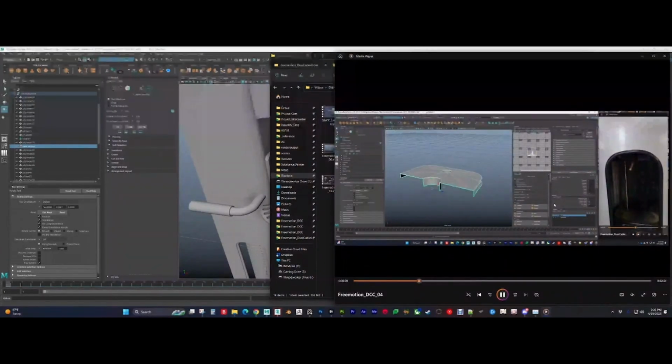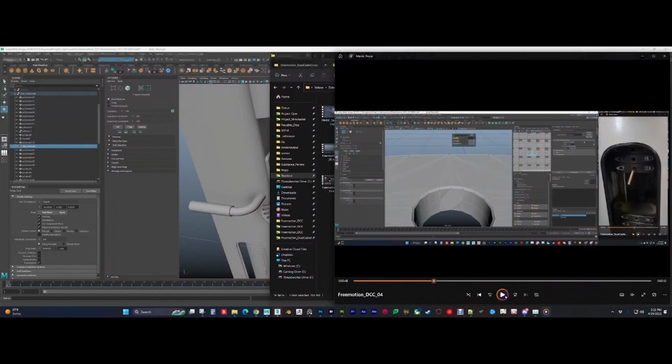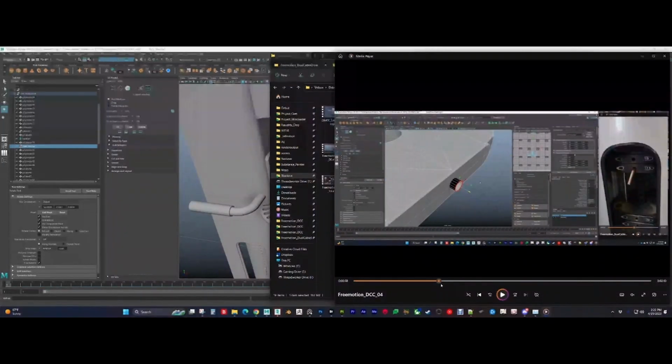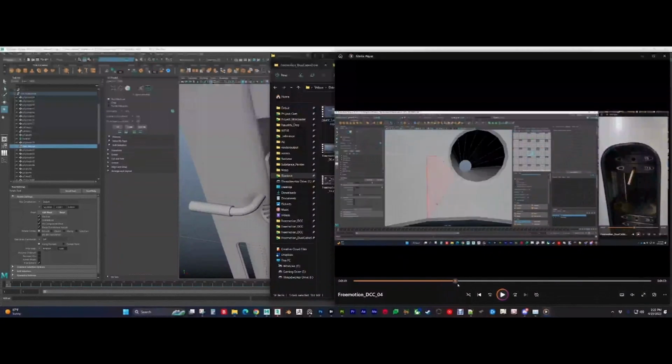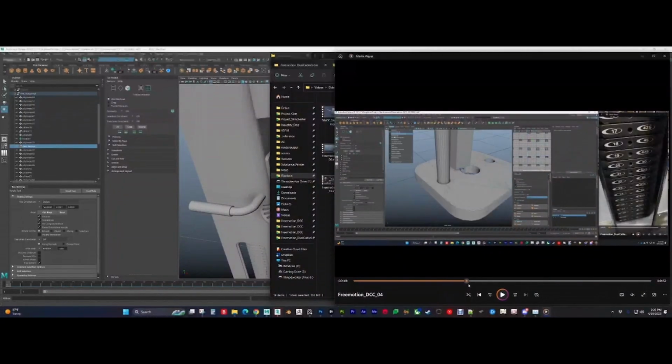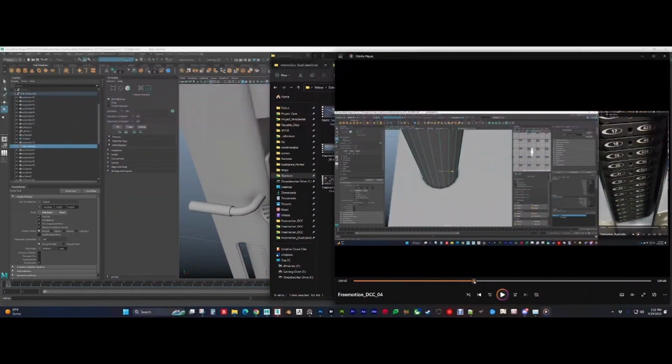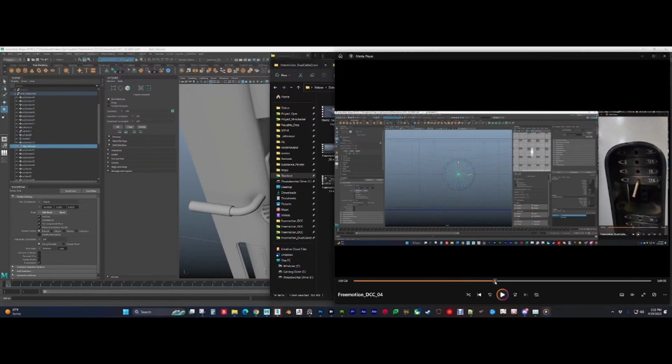And in here, I'm just showing you working in sections and kind of like quads. What I like to do is break the model into four different quadrants, and I only work on one quadrant at a time, and then I mirror it over. Just to save time, because I know this weight plate here is going to be symmetrical on at least two sides. So it's easier to go in and work on different quadrants at a time.